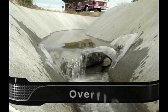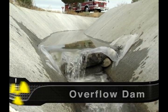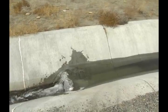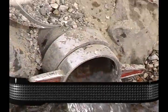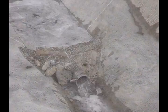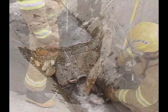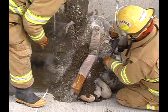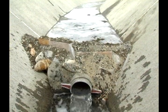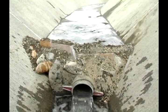Overflow dams trap material heavier than water behind the dam, allowing uncontaminated water to flow through near the top of the dam. Underflow dams trap material lighter than water behind the dam, allowing uncontaminated water to flow underneath the dam. An underflow dam may be constructed similarly to an overflow dam, with pass-through pipes placed low to allow water to flow underneath the hazardous product.